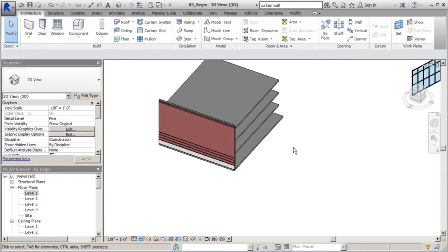And if I wanted to get my curtain wall system in place, it's real easy to do. It's just like drawing any kind of a wall in Revit. Take away the fact that there's aluminum or steel and there's glass and little clips and parts. Essentially, the behavior is the same as a wall. I can draw it the same. I can move it the same. I can highlight it and change it the same. I can go in and change the structure and parameters, and I can use the same grip to make adjustments to height and things like that.